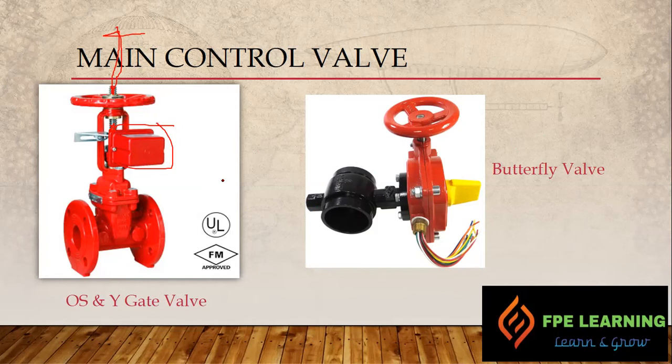These two are the control valves, right? Because of the butterfly valve, sometimes, you know, if we have a space limitation in the mechanical room or the riser room, we can use the butterfly valve instead of the gate valve, because the butterfly valve will take less space compared to the gate valve. You look at this height and compare it to this height, right? It's much less, so it takes a small space for installation. Now it is also supervised by this wire. If someone is turning it, it will give a signal.